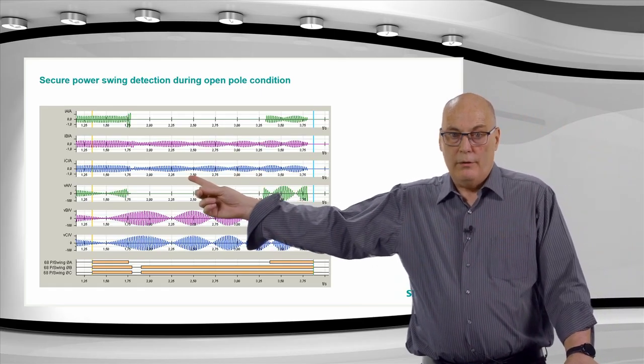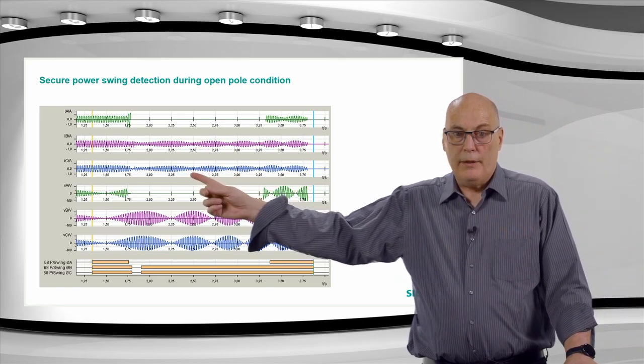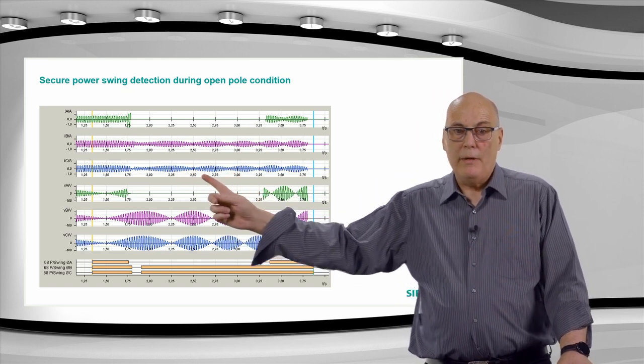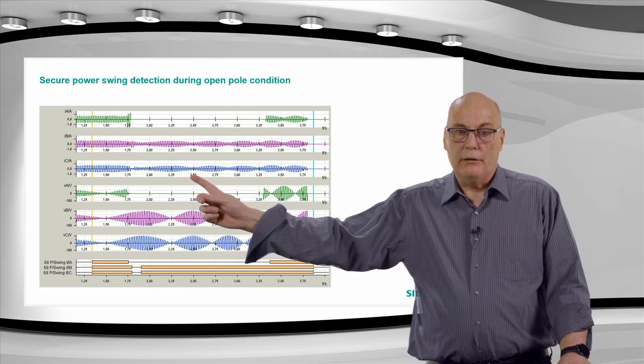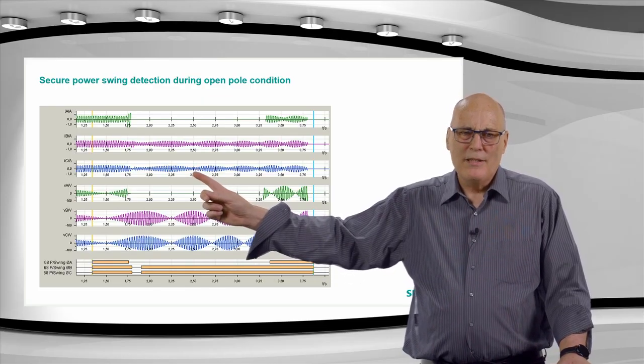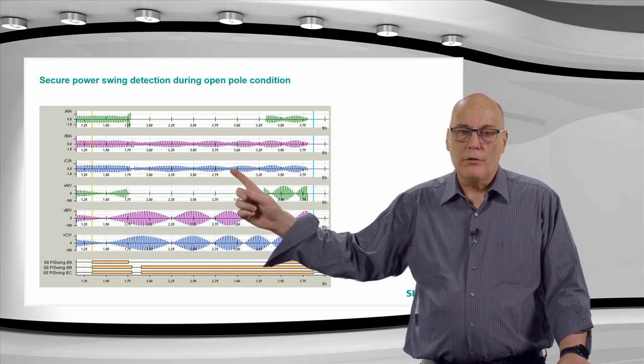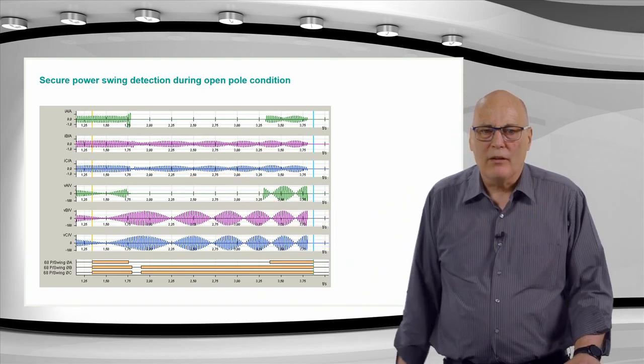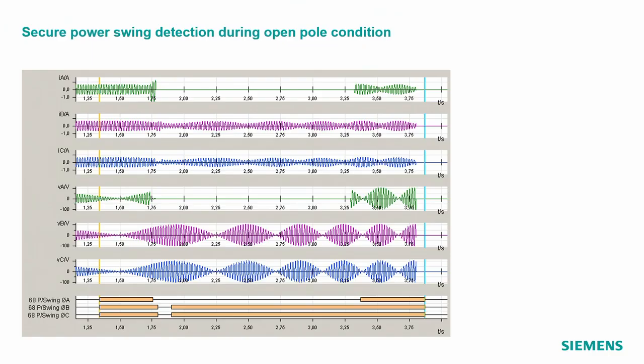It starts off with, you see, the swing frequency you can calculate from the dip here to the dip over there and the next dip over here. The time interval there, that's one rotation. That's from basically here, 0 degrees, back to 0 degrees. That's one time around the circle. And you take the time difference there, I can't read that exactly now, that would be related to the frequency. I think it's from around 2.5 seconds to just under 3 seconds, so it's just under half a second. So it's roughly a 2 to 3 hertz swing.